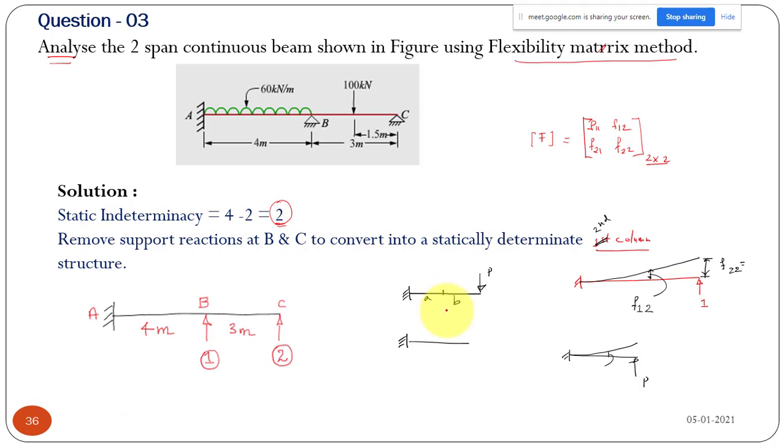I think we have a video also for that problem; we have already discussed this one. You take this load and apply an equal and opposite force here. So now what will happen? These equal and opposite forces will create a clockwise couple moment. The magnitude is P into B, since this distance is B, so this moment is PB.